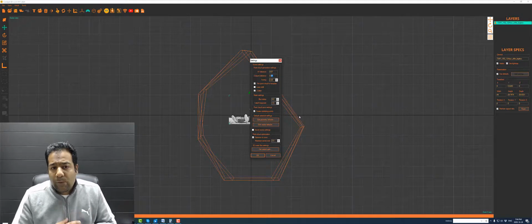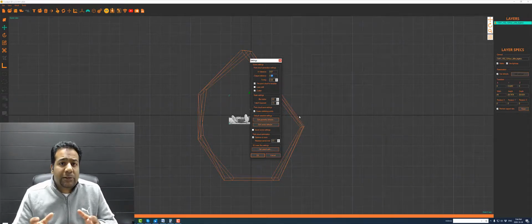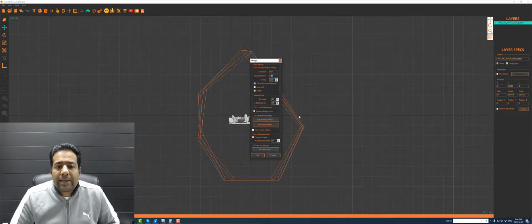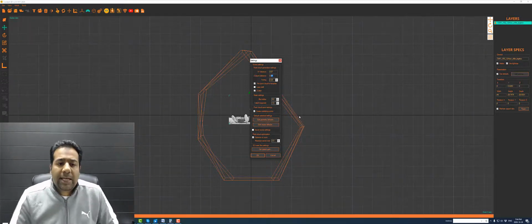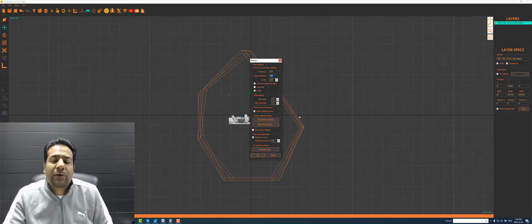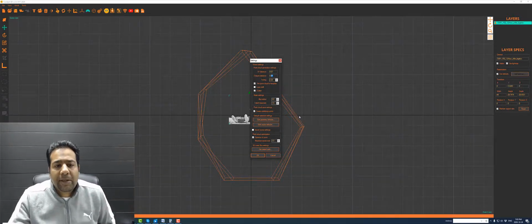Of course, the reason why you wouldn't want to do that is because it will reduce the resolution on the side view. So these are really optimal settings, but again, not really noticeable to the end consumer. If you were to double this from 0.07 to 0.14 on Z, it should be okay. If that doesn't work for you, then you can actually start doing it on XY.